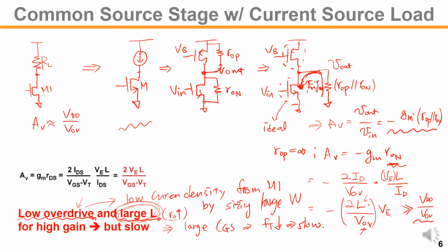So there's some trade-off between low frequency gain versus high frequency gain, whether you want a high gain in this curve, or a little lower gain. If you want higher gain in a certain frequency range, then you might want a different approach, a lower GM and smaller L for the higher midband gain.